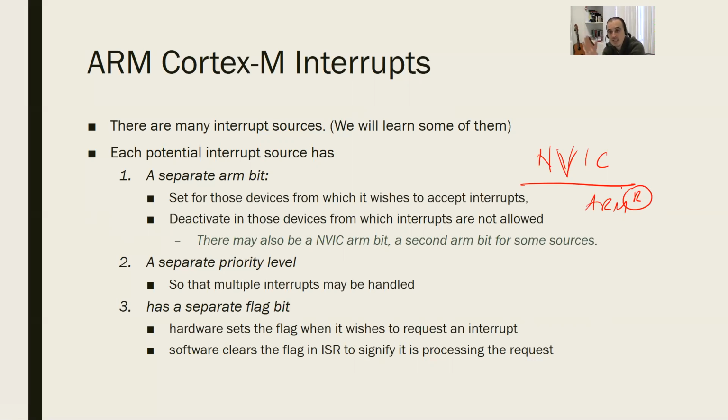What I also told you is that in the remaining part of the microprocessors course, and in your career as an embedded programmer, you're going to understand architectures or mechanisms which are attached to your device. All of those mechanisms or architectures work by changing some control bits. Similarly, to enable an interrupt in your card, you should first change some control bits so that necessary modifications are done and your system will be able to accept an interrupt.